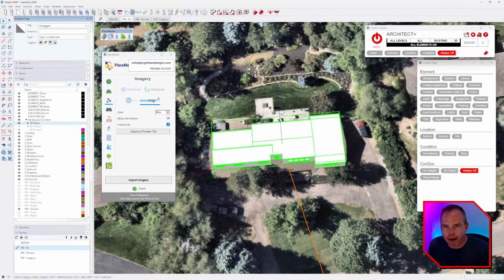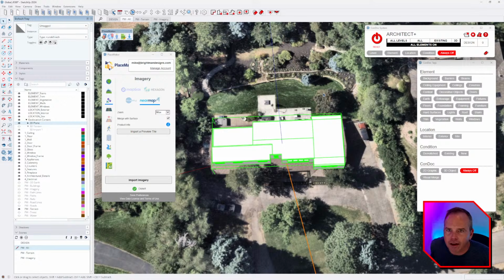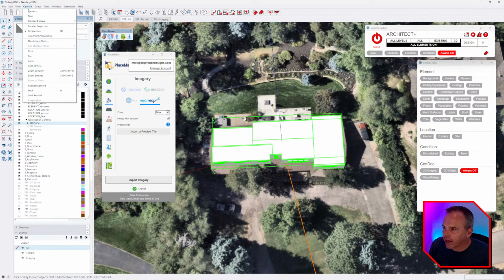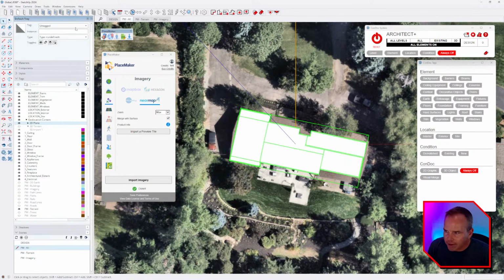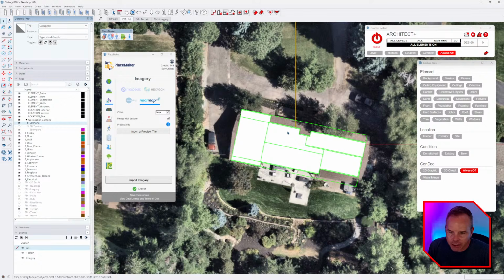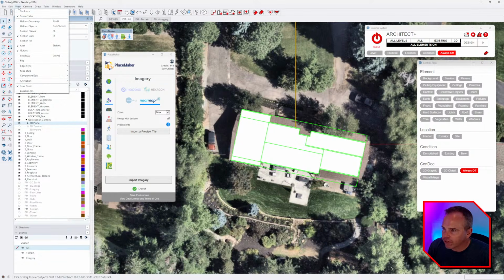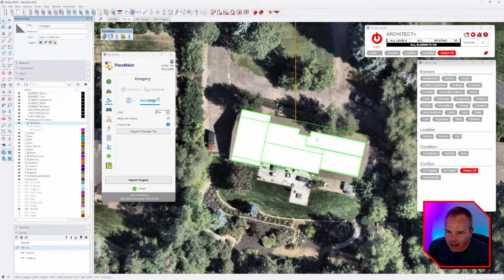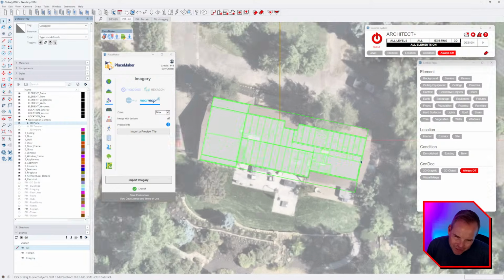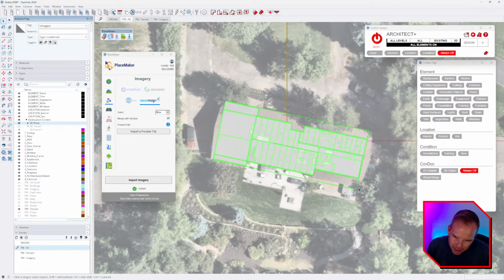We're just really worried about where it sits on there. And you know what? Yeah, Keenan, you're right. We could go to camera, standard views top, camera, parallel projection. And then we could even go to view, face style X-ray. And that would kind of help a bit. Yeah, you're right. We could have done that, and that would have helped shore it up a little bit.